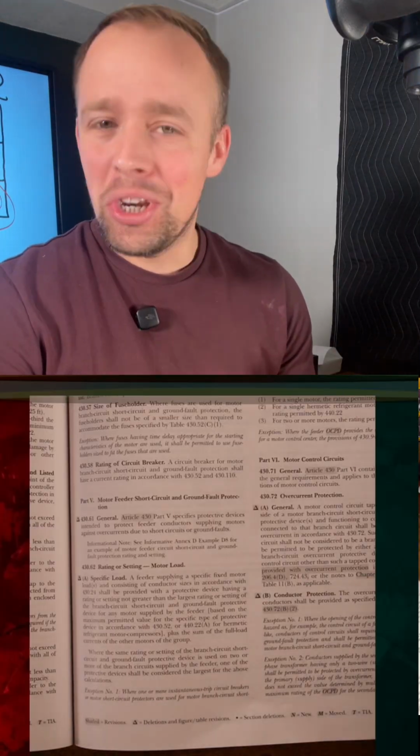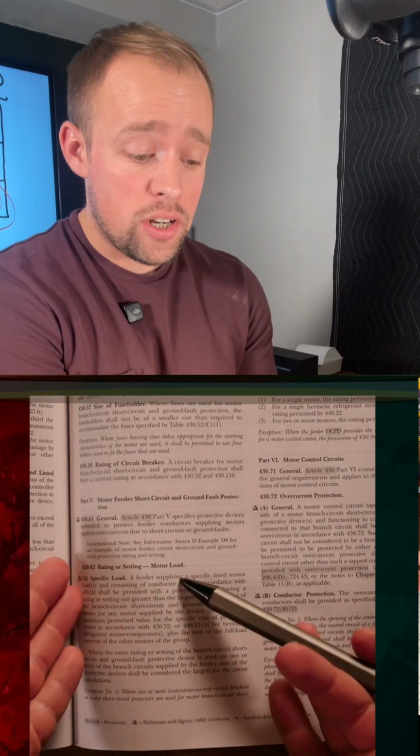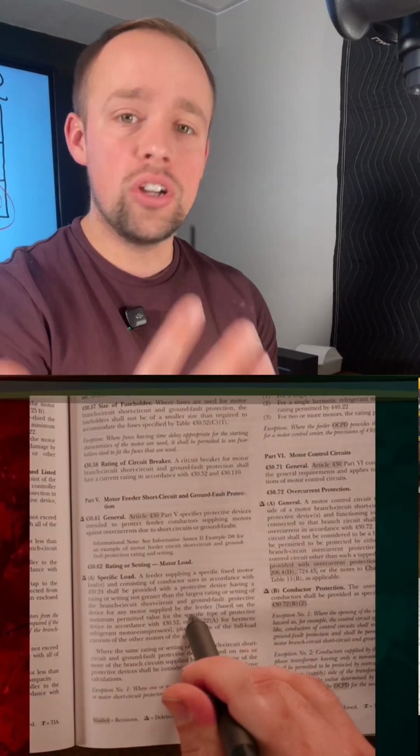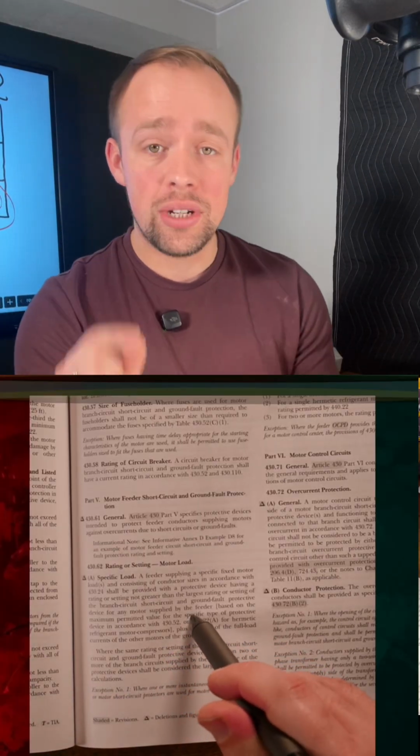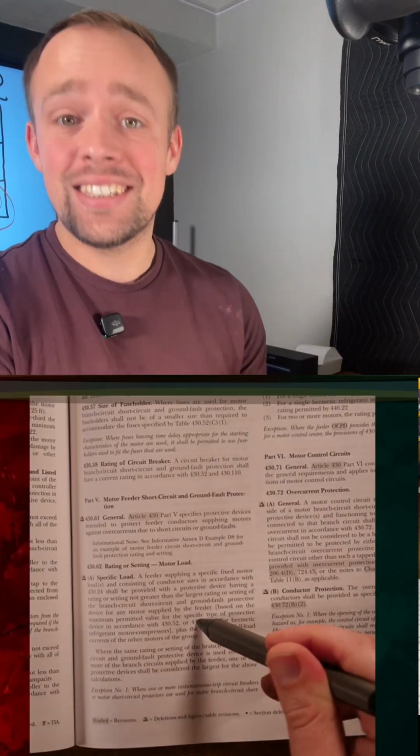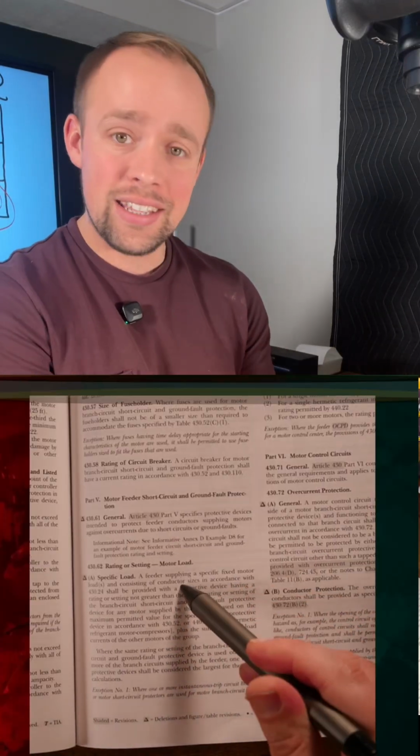Comment down below if you want me to do a video explaining that, but in this video I just wanted to describe this. Whatever it's telling us to calculate, the ampacity that you conclude, we have to select an overcurrent protective device that does not exceed that number. If you do, it's too big, it's a code violation, we cannot exceed that number.